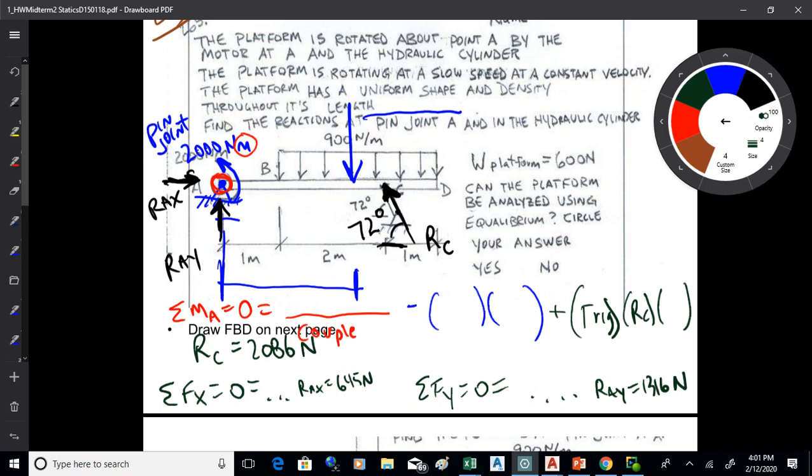And you're kind of going through a series of steps. You're first breaking down those forces into simpler forms. It's kind of a resultant kind of thing that you're doing there. You're not really doing a full resultant, but you're breaking each individual force down. And you're representing those supports as forces. Okay. Once you do that, then you run an equilibrium equation, usually starting with a sum of moments equal to 0, about a point that has two unknowns, and then a sum of Fx and a sum of Fy is a fairly common pattern on this.